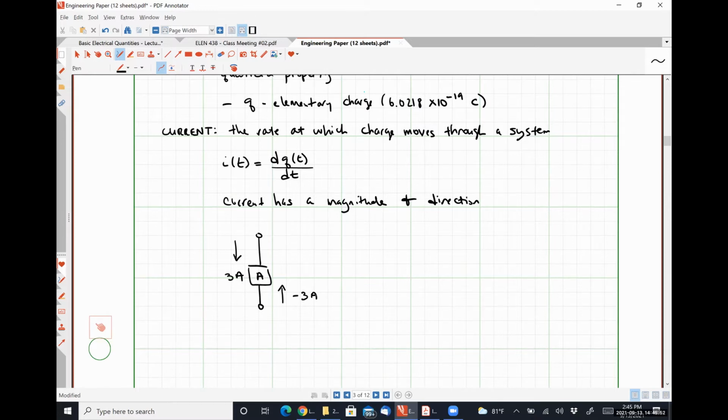So we can see here from this simple example that if we're ever given a negative current, in order to convert it to a positive current, because sometimes that'll make our math a little bit easier, not carrying around as many negative signs, all we have to do is change the direction on the arrow, right? So changing the direction of the current flow is the same as multiplying it by a factor of -1. Those two are the same operation, just one is mathematical and the other is graphical, but they mean the exact same thing.